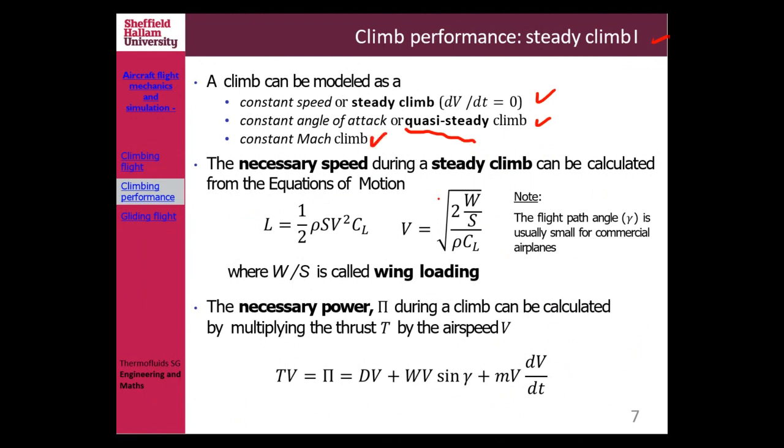And of course, the third one is perhaps related to the fighter I mentioned, because if you climb with a commercial passenger aircraft, the maximum, as I said, in order not to upset your passengers, is about 2,000 feet per minute rate of climb. Then that will not really cause a significant change in Mach number.